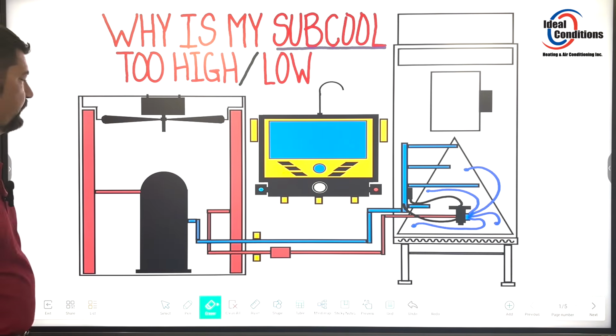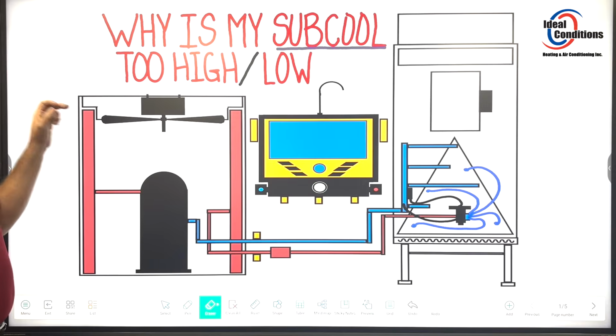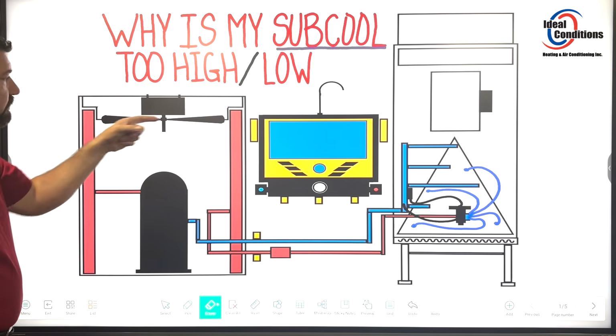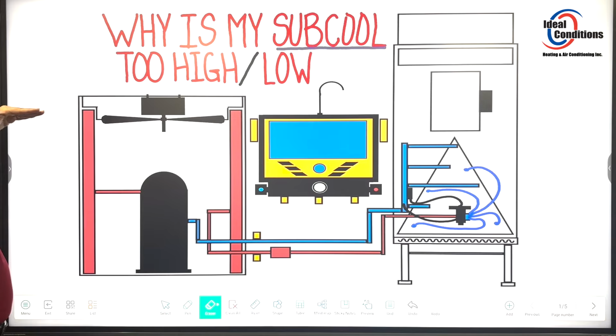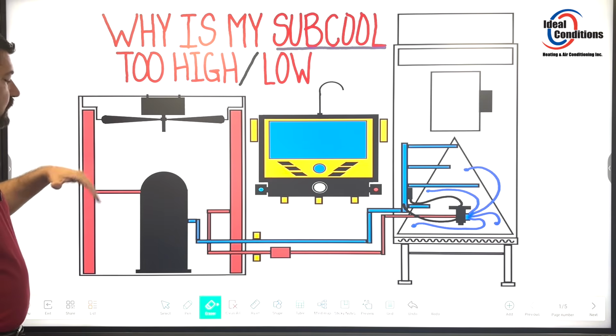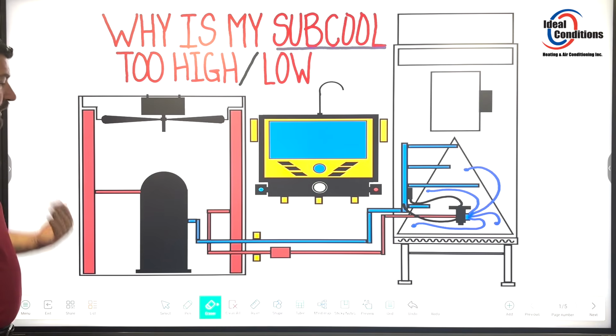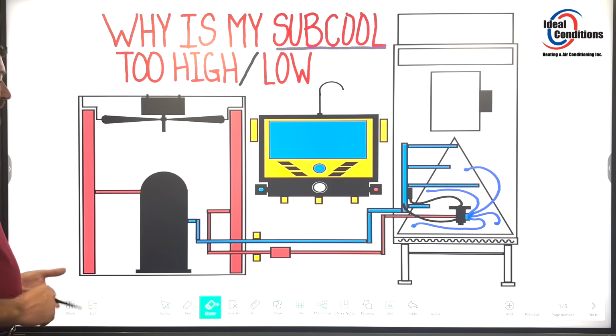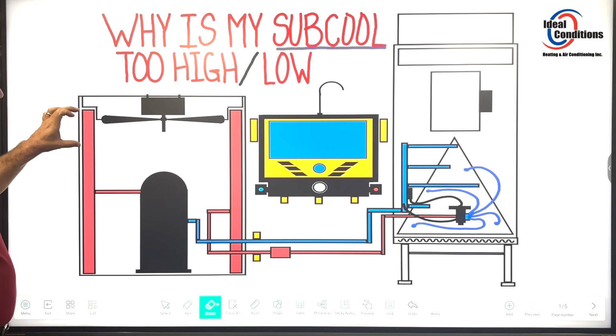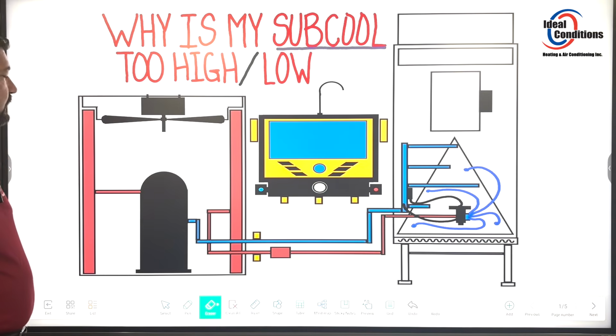Let's look at a condenser. You can change this condenser motor out, and as you can see here, I got a fan shroud, and if that fan blade is not sitting properly up in that shroud, then the airflow that's going across this condenser coil may be missing an entire section of coil, which will drop my subcool value, all right? And so I might be fighting uphill trying to achieve the proper subcool or maybe get subcool, and maybe I can't get more than a degree of subcool, right? Because maybe this whole top section of condenser coil is still vapor leaving it.